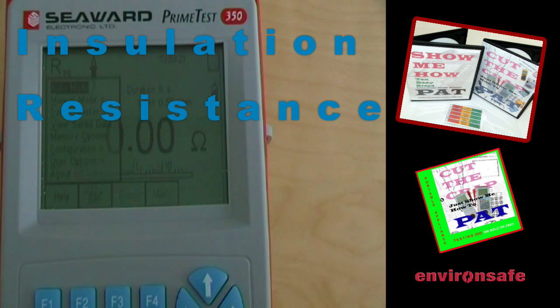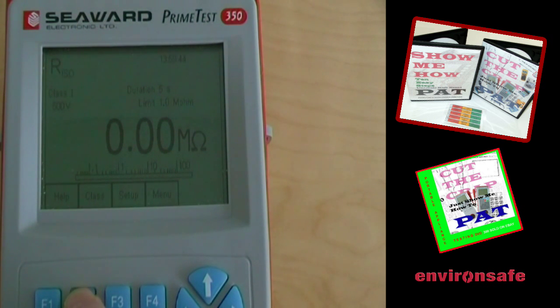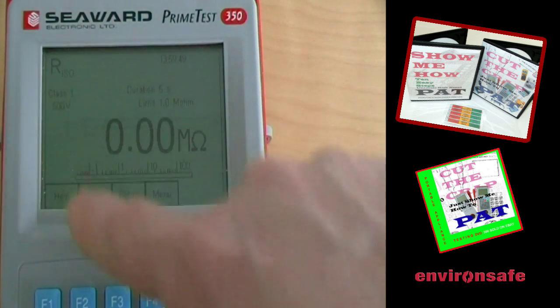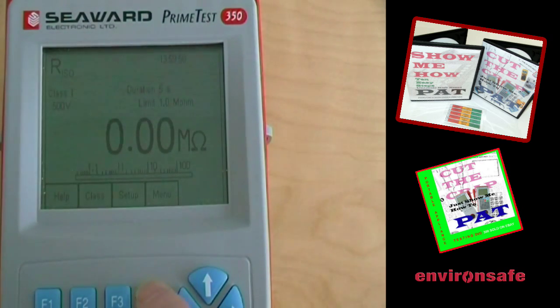Select main menu, manual mode, F4 to OK, insulation resistance, F4 to OK, and the choices we have here are F1 to help, F2 to choose the class, class 1 and class 2. If you just check here, you'll see that it will change. Class 2, class 1 at 500 volts, which you can just see here.